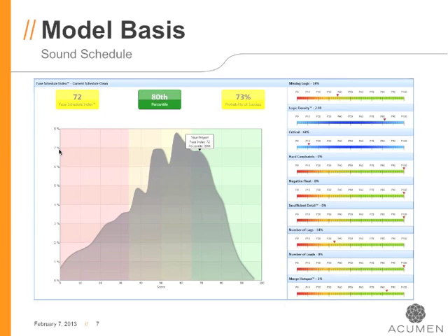Now, I mentioned earlier that we believe, first and foremost, a sound basis of schedule is king, and secondly, you have to take into account risk and uncertainty in forecasting. So before a schedule risk analysis is run, it's very important to make sure that the underlying schedule is a free-flowing schedule. In other words, we need to make sure that there is continuous logic through the plan, that there isn't contingency or buffer already baked into the schedule, and that the dates aren't artificially constrained.